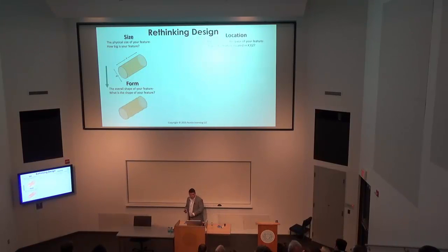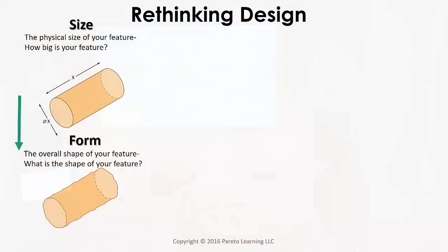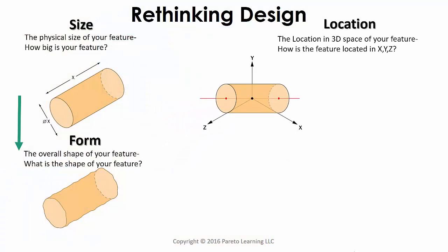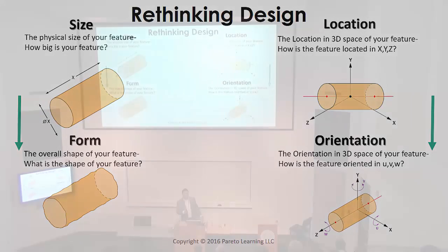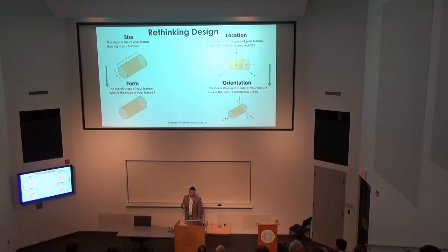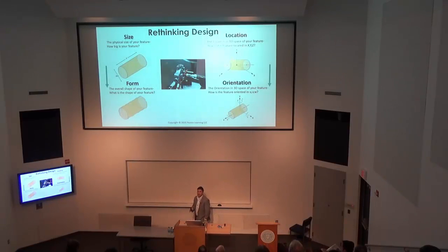Then we have our relatable dimensions, our relatable types of features, which are location and orientation. These are big ones that I was completely missing. I would put an angular dimension on something, plus or minus so-and-so degrees, to give it an angle. But I was never quite trained that these 4 fundamentals are what truly make up a part design. And this is what we should be teaching, because these are the 4 fundamental elements of GD&T. You can't have any of the 14 main symbols without these 4 core elements. Every symbol is either a combination or a specific form of them.